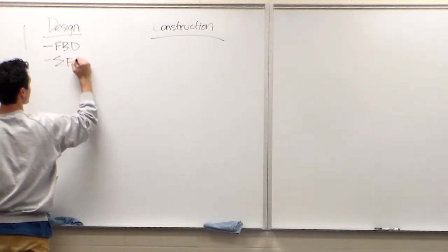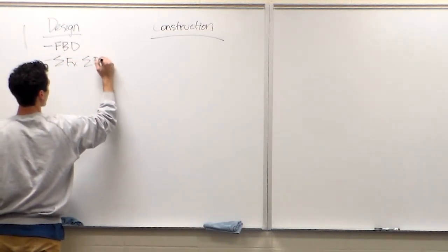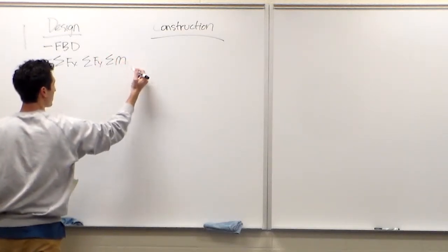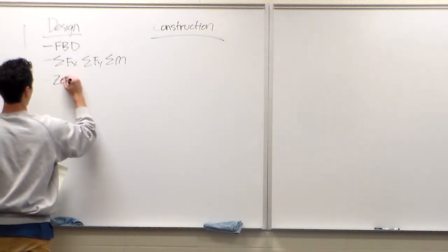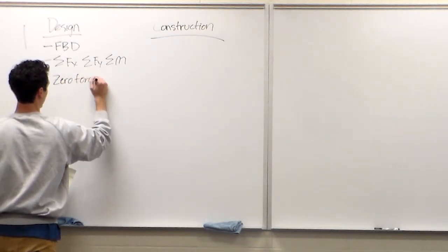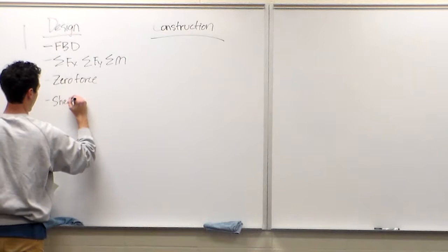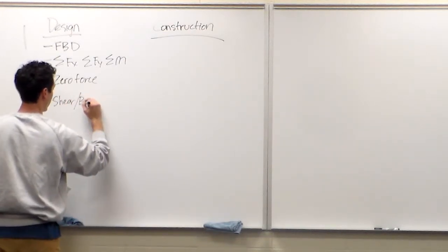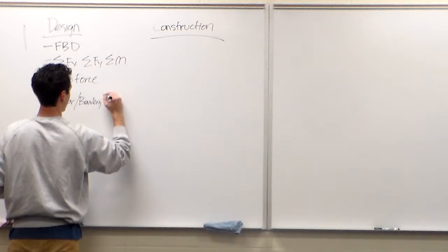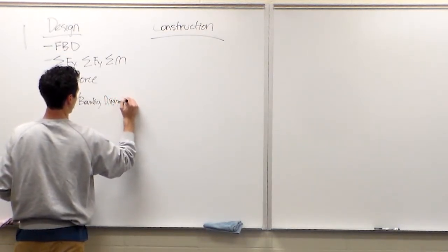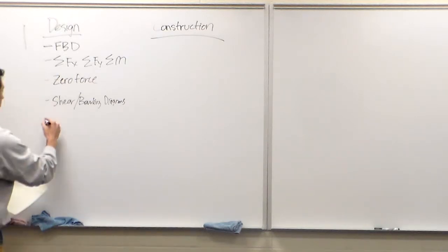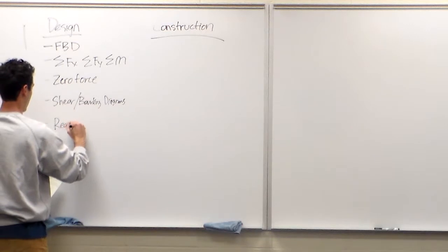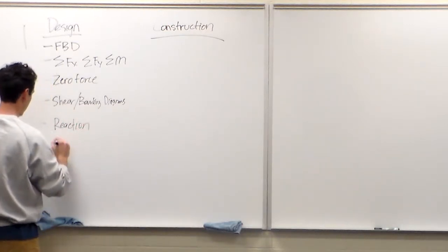We have some of the forces in X, some of the forces in Y, some of the moments. What are some of the things you guys think you could use? Make sure we don't have any zero force members. Good. You could use shear and moment diagrams. Perfect. Shear and bending diagrams. Anything else you guys can think of? Find the reaction forces. Good. Reaction forces,